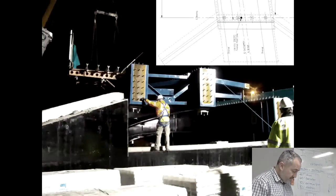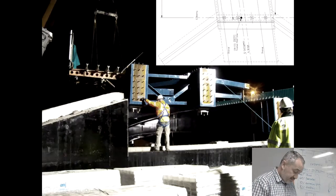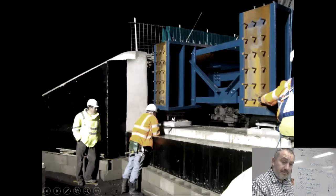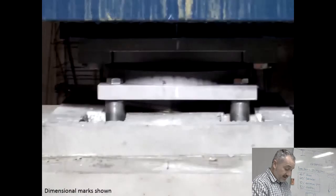So back to our bridge. We've got some sort of K bracing. These shear studs will fit into the concrete of the abutment. They had people on standby just in case the bearings didn't fit. And they've got some steel shims, so they can get it right horizontally in terms of the height, depending on how much it dropped. So it's very similar to putting in steel columns for a building.